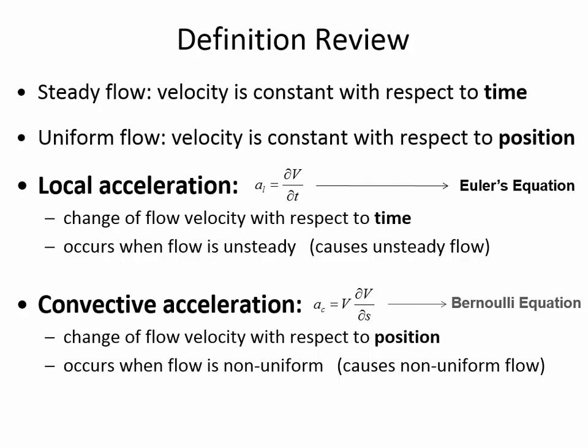And so if I was going to draw a picture of a tank, for example, here's a sealed tank, and here's location 1, and here's location 2, and let's say the tank isn't moving. It's just stationary, it's static. And so if we wanted to know the change in pressure between the two, and here is up, all we'd have to do is measure the delta H between them, right? So that's no big issue. The change in pressure would be delta H times gamma. So that's the hydrostatic equation. But what if this was experiencing a local acceleration?